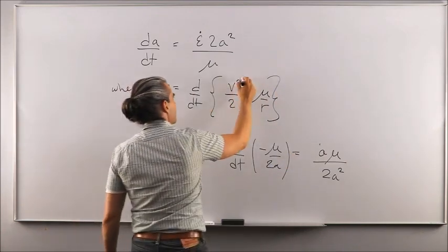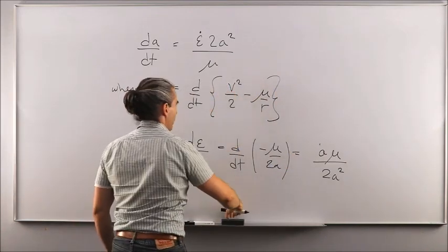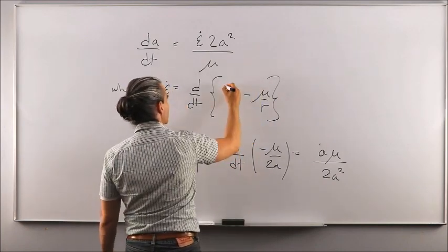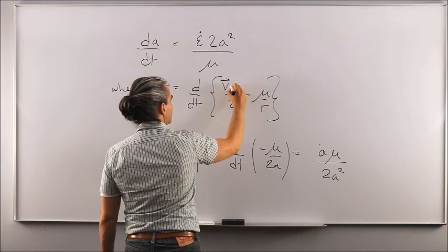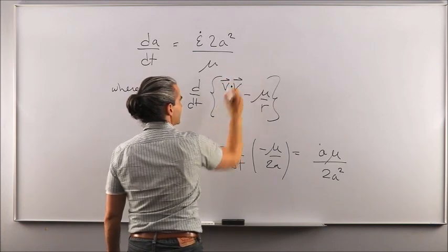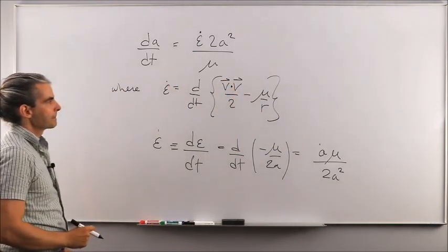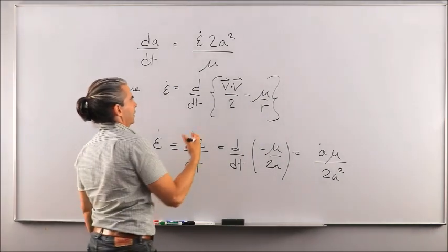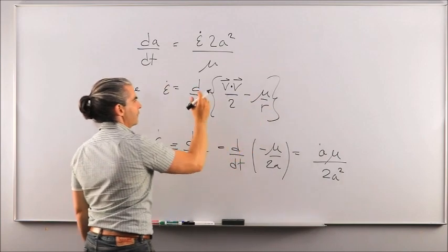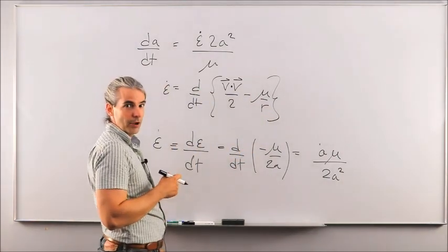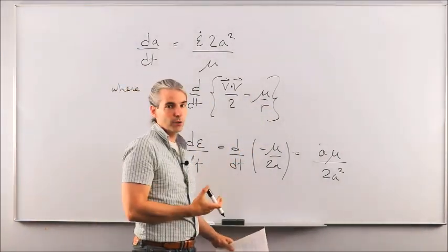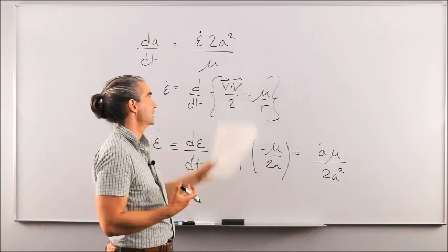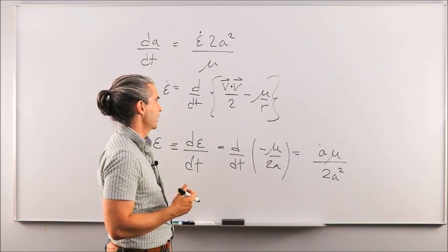But here, instead of writing the speed squared, we're going to write it slightly differently, and specifically we're going to write velocity dot product with itself, okay? Because we need to arrive at a point where we have v dot in the expression such that we can use a two-body equation plus the drag perturbing acceleration and see the effects on our semi-major axis, okay?